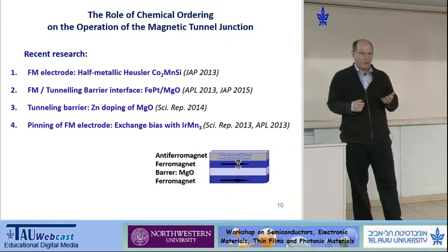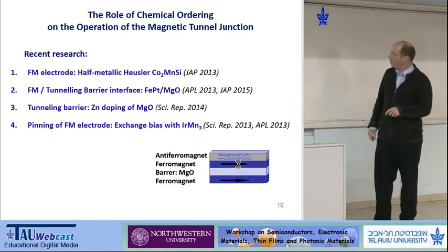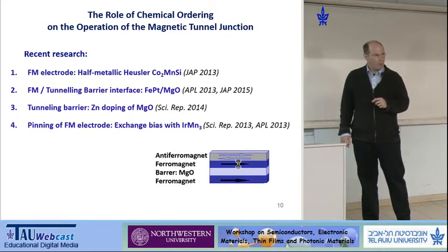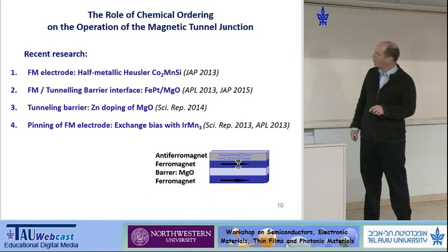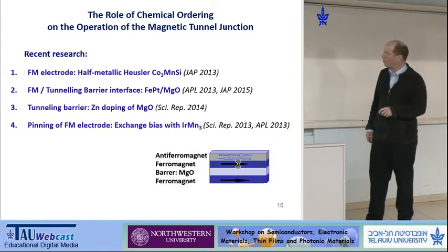And this is in order to combat issues of thermal stability. It's done by using very high magnetocrystalline anisotropy, and of course to get higher areal density. So actually new sensors have to look for electrodes where the magnetic moments are also perpendicular. And one such potential material is iron platinum. It's L10 ordered, not a simple alloy. So that's another topic.